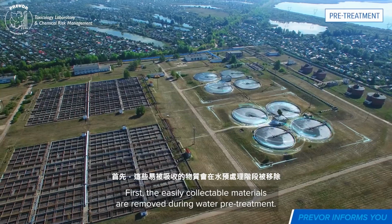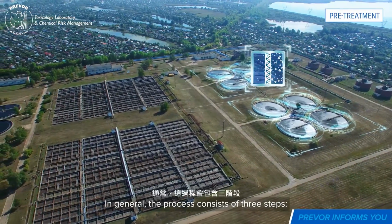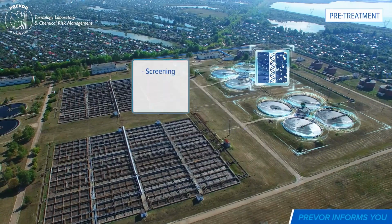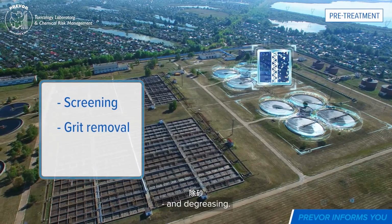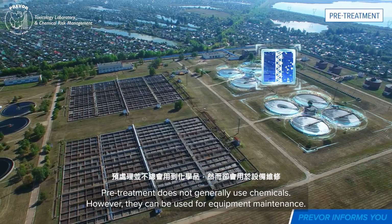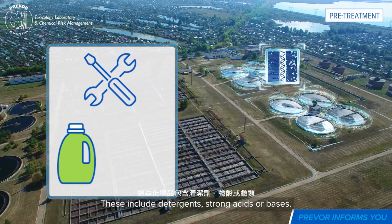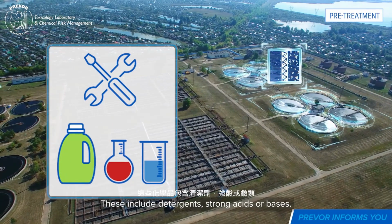First, the easily collectible materials are removed during water pre-treatment. In general, the process consists of 3 steps: screening, grit removal, and degreasing. Pre-treatment does not generally use chemicals. However, they can be used for equipment maintenance. These include detergents, strong acids, or bases.